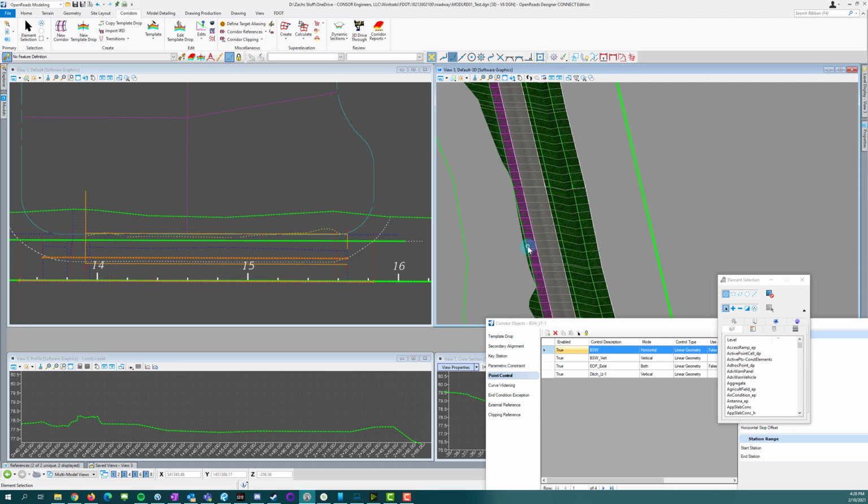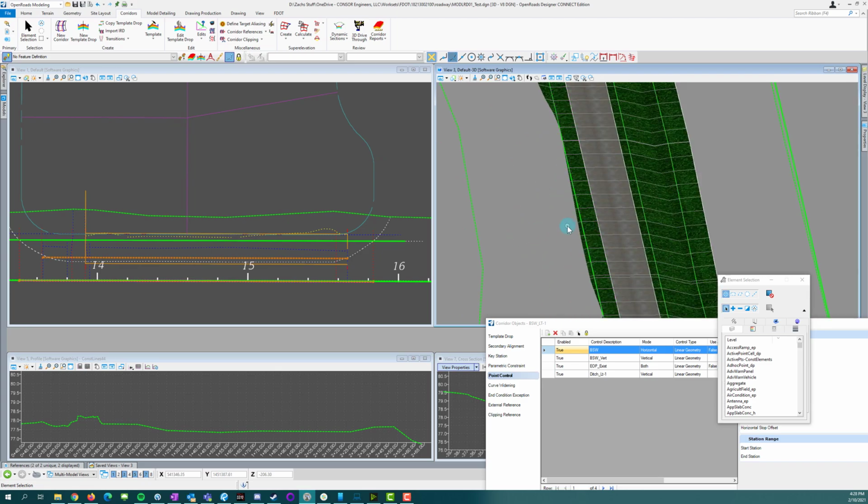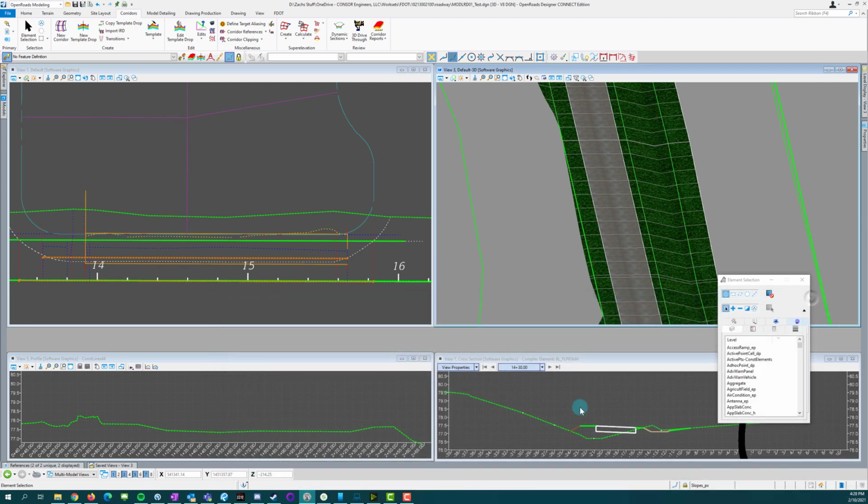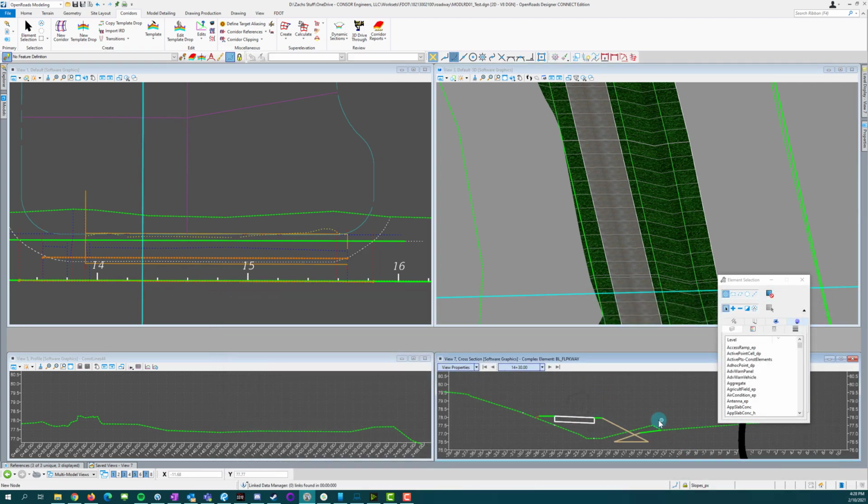Maybe also here that we could make it go straight across and into the slope instead of tying down. That's another option we could do with the template. Let's look at that real quick. So like I said, instead of trapping water here, we could just bring this all the way across, and then the water would flow down, hit the flat, come down into here. The real issue here seems to be this ditch.